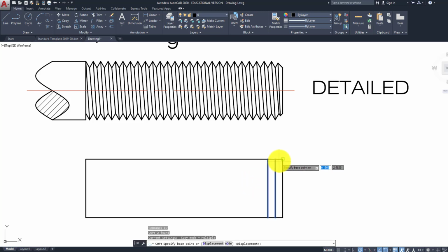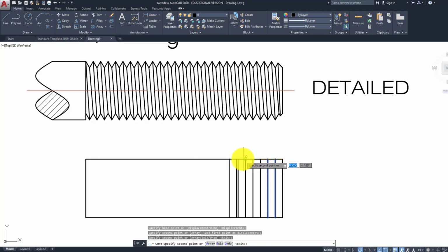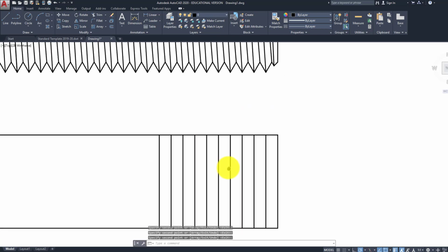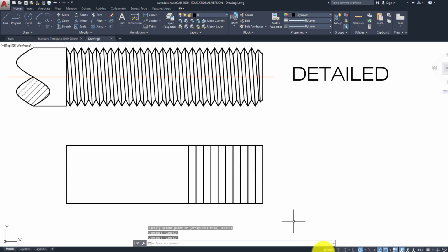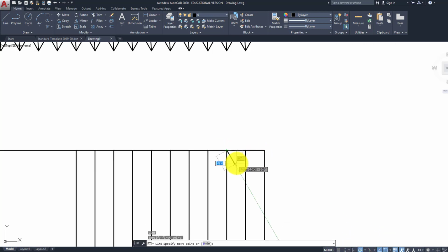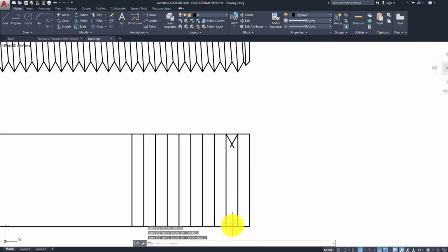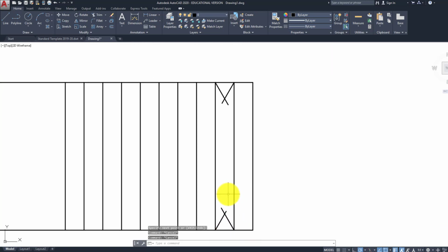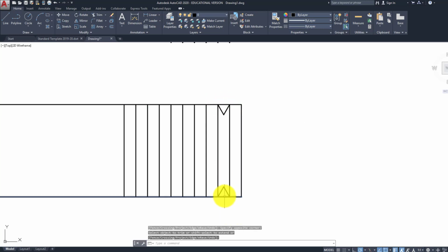And instead of drawing the slope and that curl and all that fun stuff, what we're going to do is jump into this polar tracking. And what you do is you go down just like before, but you do the exact same thing. I'm just going to do it in one thread. Like that. TR, enter. Trim that up so we got our major and our minor diameter.